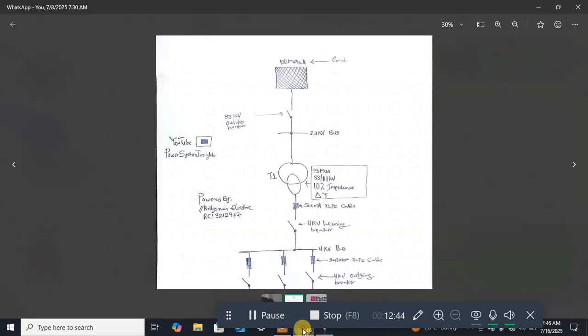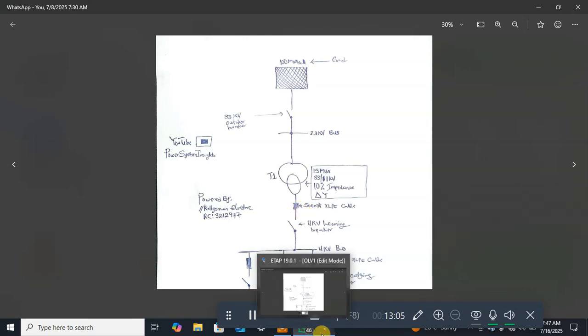So for 700 and something amps, which you may not operate the transformer at full load, so you will not load the transformer 100%. So if you use 500 for such load, I think it should work.